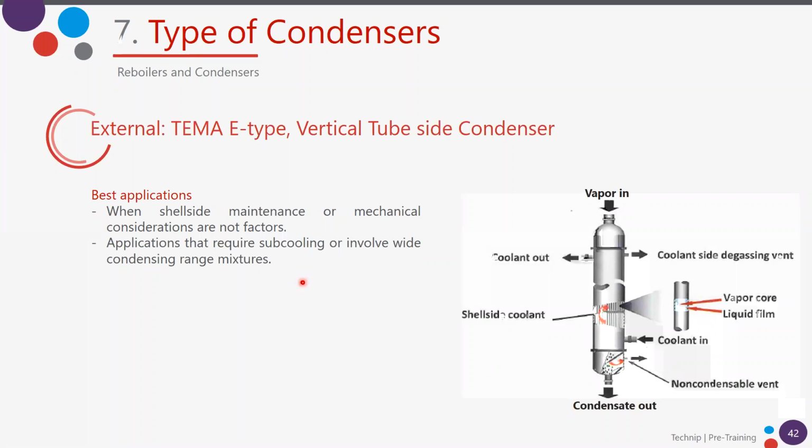So the best applications are when shell side maintenance or mechanical considerations are not factors, and also applications that require subcooling or involve wide condensing range mixtures.